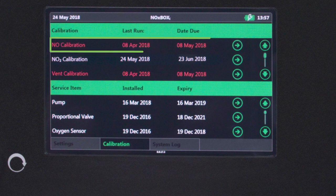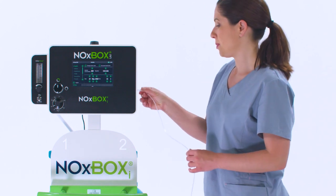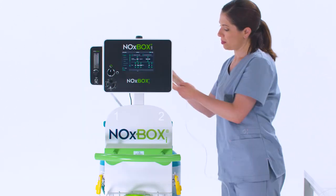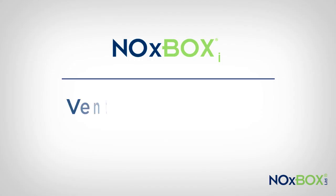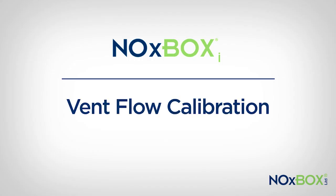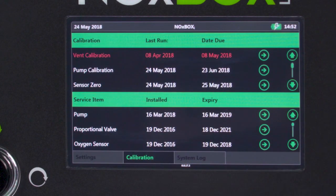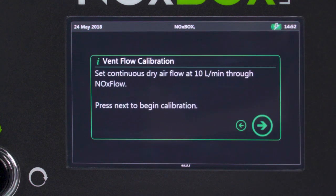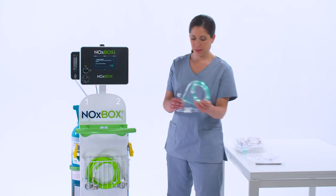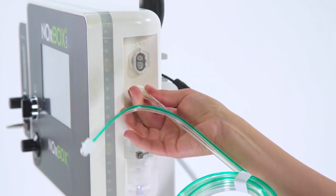Next, calibrate the nitric oxide sensor following the same procedure. Once both the nitrogen dioxide and nitric oxide calibrations are complete, remove the hydrophobic filter and place it into storage. Finally, to perform the vent flow calibration, press the on-screen Calibration tab and select the respective arrow.